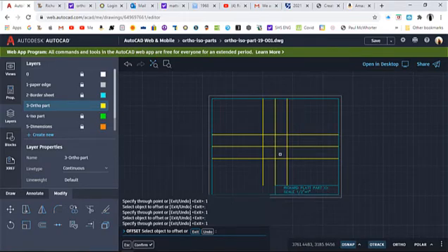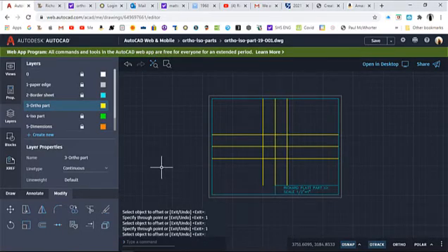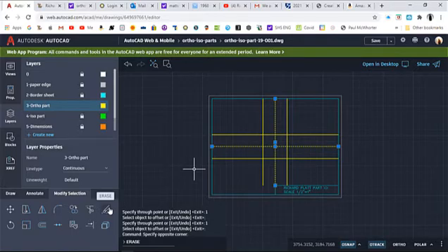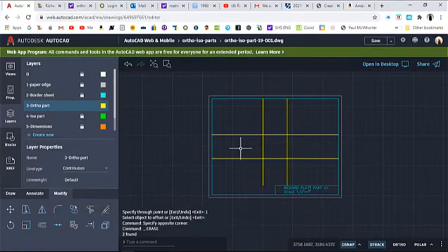So now what I'm going to do is I'm going to confirm that, and I'm going to come up here and I'm going to draw a polygon holding my mouse down from one end to the other. Now, in normal AutoCAD, you would have to do point click and then point click to create that selection. So I went ahead and deleted those. Okay, good. Using the erase command.